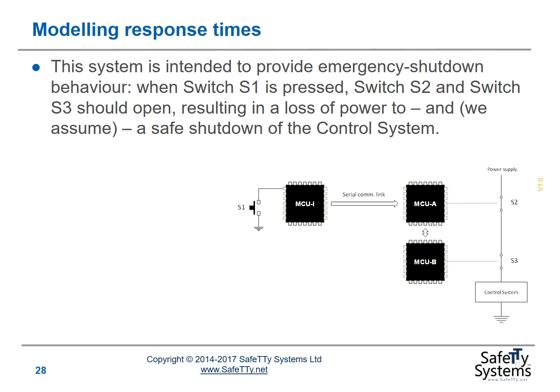And what we're doing here is we are increasing confidence in the processing of the received messages by double checking them on the 2 microcontrollers. So we have a single communication link that runs from MCU-I to MCU-A. When messages are received by MCU-A, MCU-A doesn't take action immediately. Instead, MCU-A checks that it's happy the messages are correct.